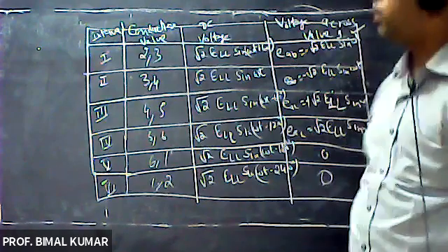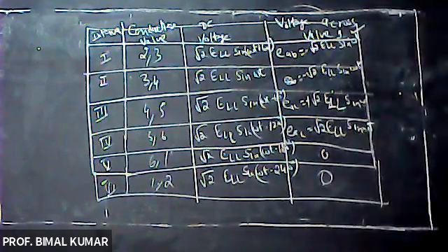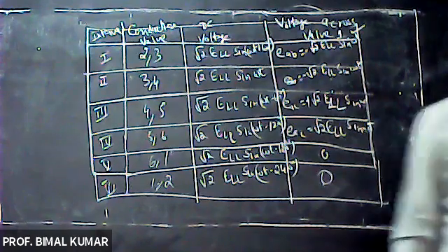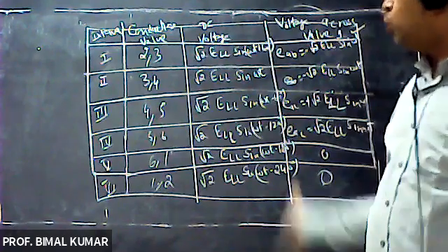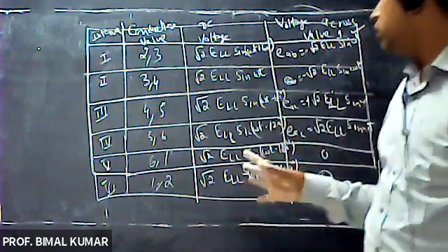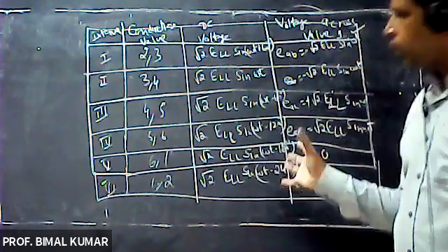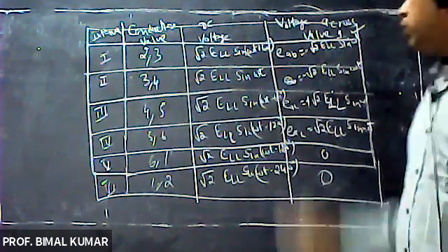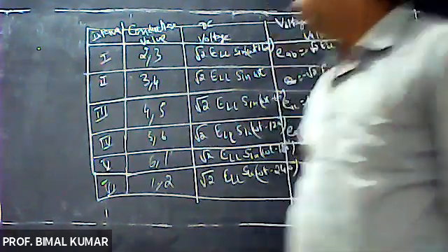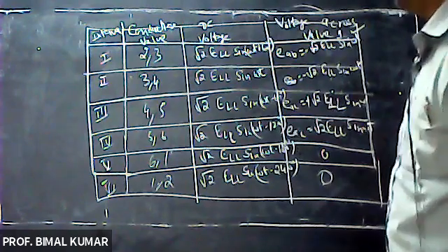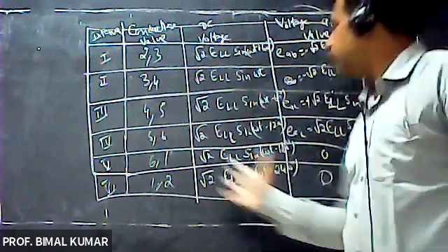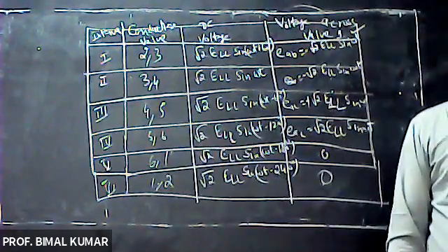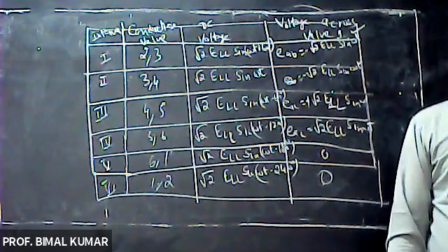Whenever the thyristor will conduct, it acts as equivalent to a short circuit or on-state switch. During this condition, the voltage across the device will be 0, because its anode and cathode will both be at the same potential, during interval 5 and interval 6.